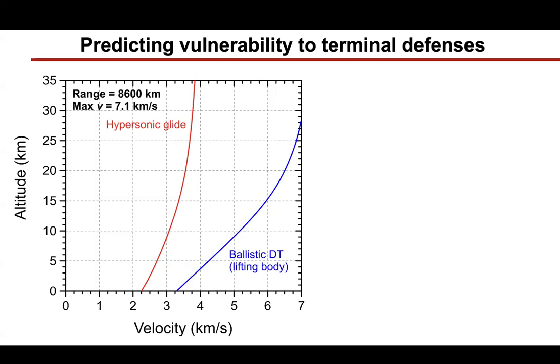ways. So if you're thinking about evading defenses, what this tells us is again, in direct contradiction to that conventional narrative, there seem to be some clear advantages to using a more traditional ballistic missile system because in the terminal phase, you're maintaining much higher velocities since you haven't been subject to the effects of drag and the velocity losses that stem from that. You have better capability in many cases to try to maneuver around and dodge incoming interceptors.